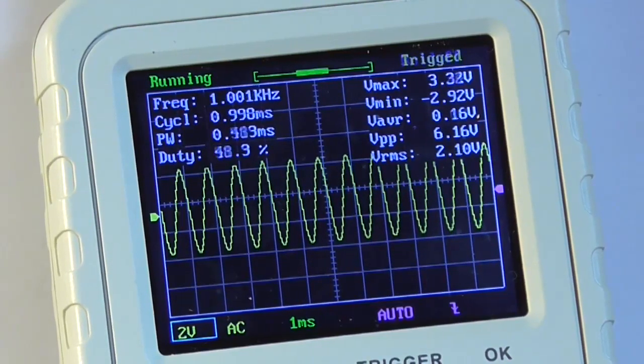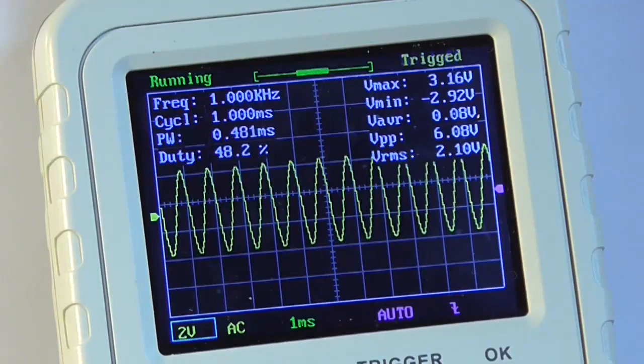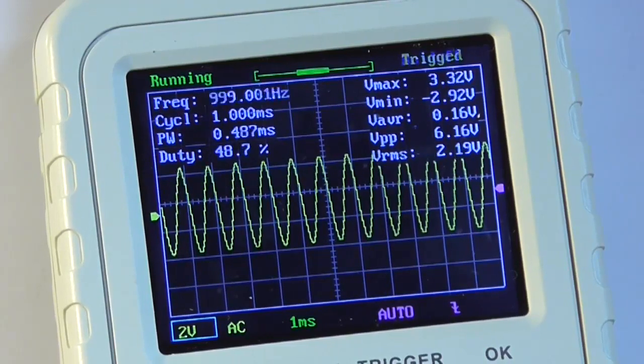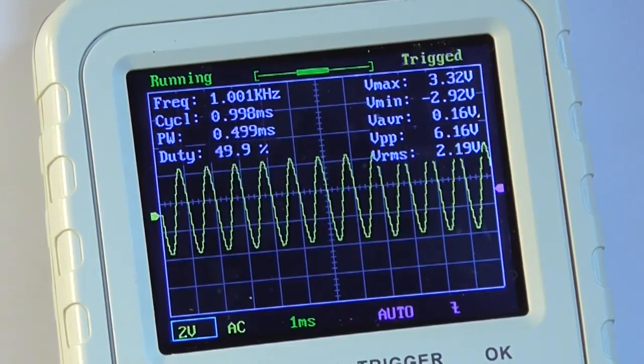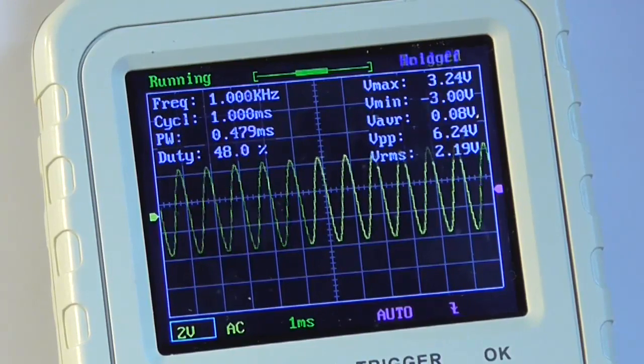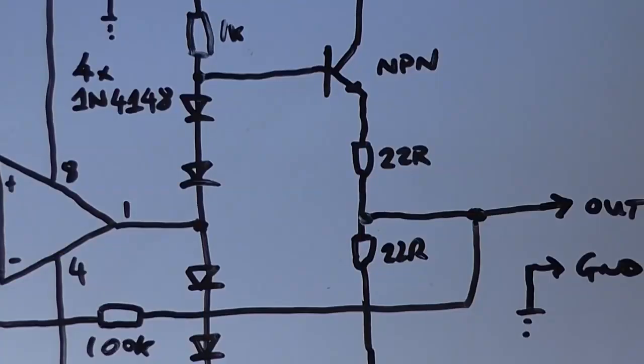We're at least a good 7 to 8 volt difference from the peaks to the plus minus 15 volt rail. And that is attributed to the drop in the transistors, as well as how hard they're being biased on, and those two 22 ohm resistors.